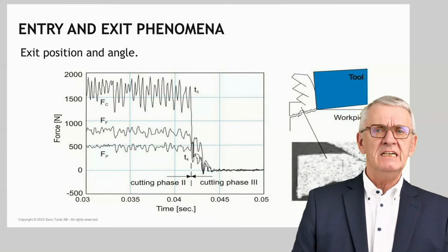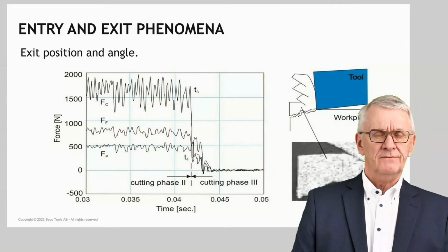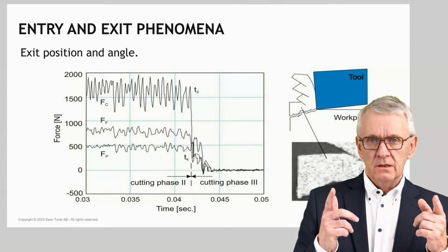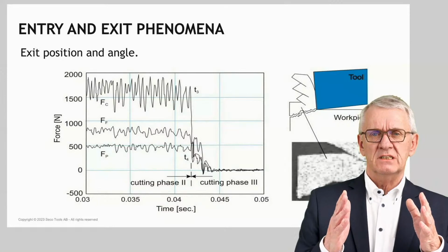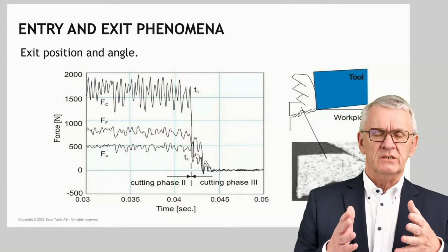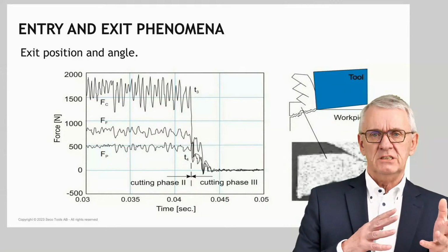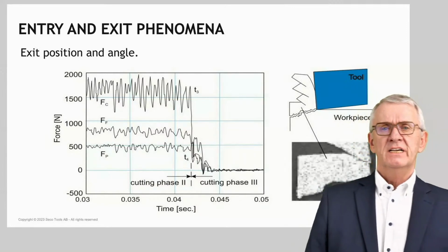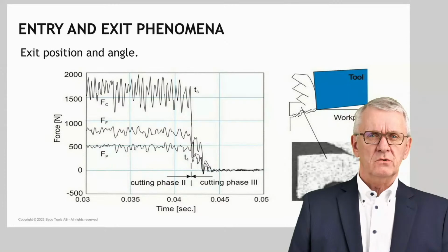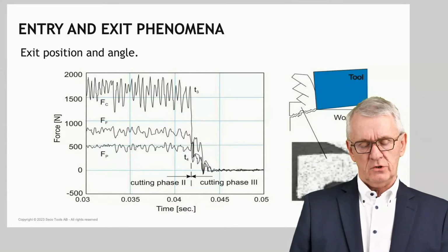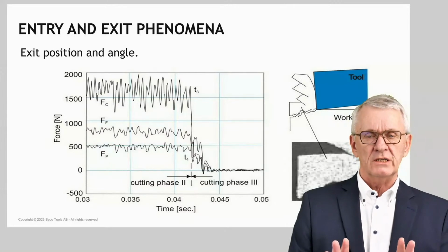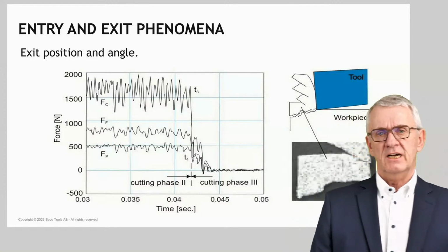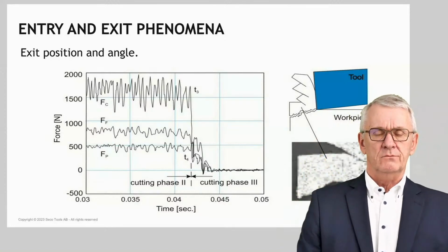But when a cutting edge leaves the workpiece, for a fraction of a second, but each rotation again, it could happen that pressure changes into tension, like there is a pull on a cutting edge, and most cutting materials of today have no resistance whatsoever. So what could happen at exit is that, and I am exaggerating, I know, your cutting edges kind of explode when they leave a workpiece. It's like they are pulled apart.